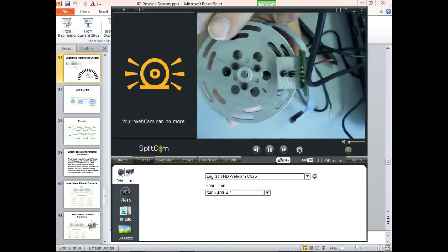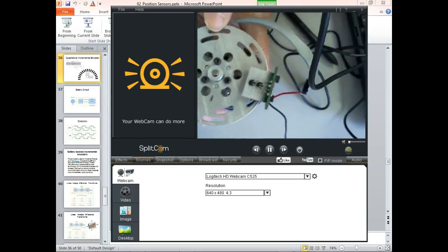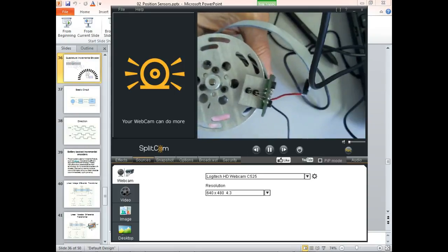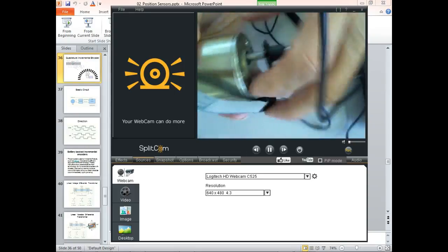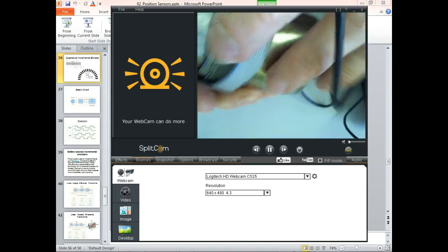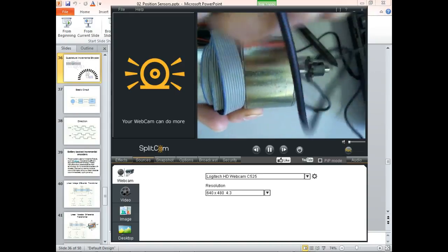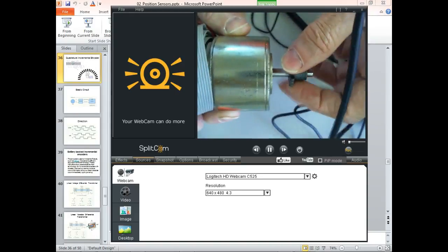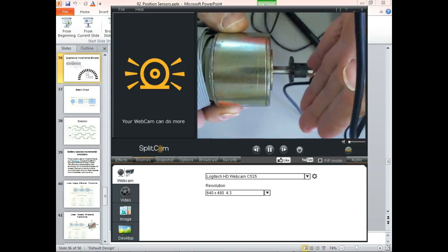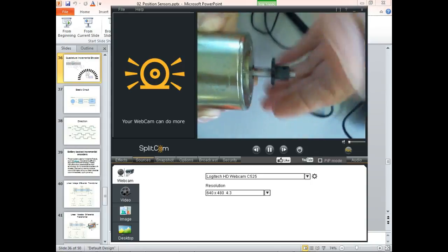It looks like this has a very poor resolution, but the actual actuator would see this as 1/65th of the size, right? You understand? So it sees it as a tiny thing because it goes through the gear. So the actuator is actually out here after it goes through the 65.5 gear reduction. So what are we doing here? If we drop the speed down, what do we increase? Torque. Yeah. So we're getting the same amount of work, right? You understand that? So this guy here would be a torque multiplier, and it's going to be a speed divider.